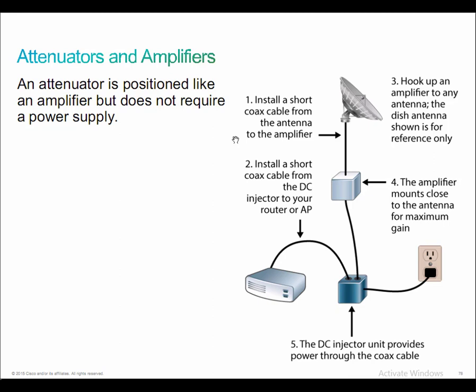All right. If it turns out that you have, for some reason, I don't know why this would happen, a signal that is too strong and you want to make sure that you're meeting the regulations and requirements, you can install an attenuator to reduce the transmitter signal. Now, attenuators typically don't always have to be active.